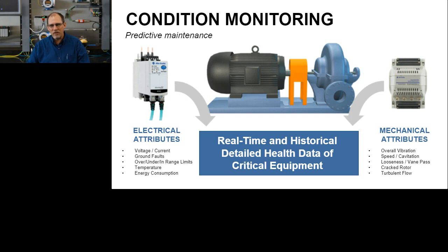I can remember one time when we saw a bearing, and with these vibrations you can actually detect: is it the inner race, is it the outer race, which bearing is it? We detected that a bearing was going to fail. I remember this because we were working over the weekend and late at night. We caught it before it failed, and we said, okay, on Friday night we're going to shut down and get the line back up and running. I remember the bearing had gotten really hot. It actually had fused the shaft, so we had to cut it off. We got this all done on a planned downtime.